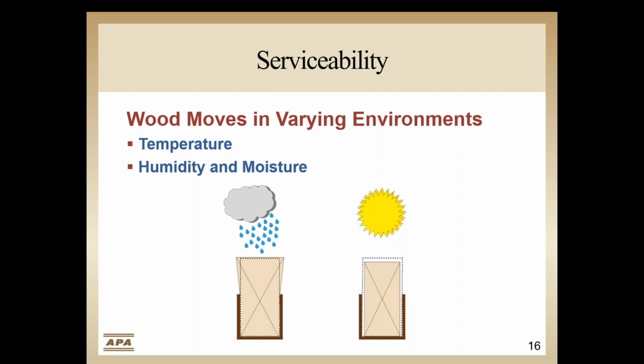Shrinkage can loosen bolted connections or increase instability in hangers. Swelling can deform connection hardware and cause other geometric problems. Day-to-day temperature changes generally don't play much of a role in disrupting the connection's life. However, extreme changes in short periods of time can, especially if there's a lot of metal hardware in the connection, as metal and wood have very different thermal expansion coefficients. This difference can cause some grief if not taken into account for extreme conditions.